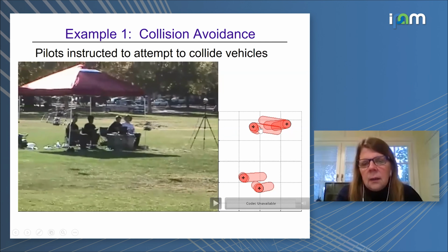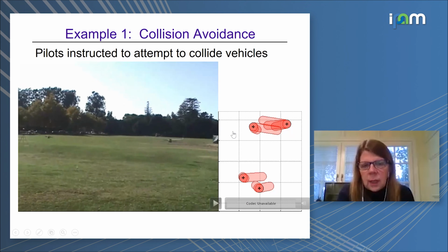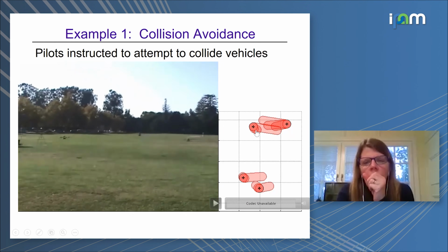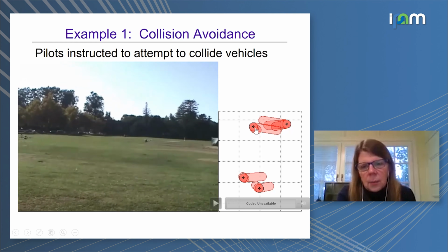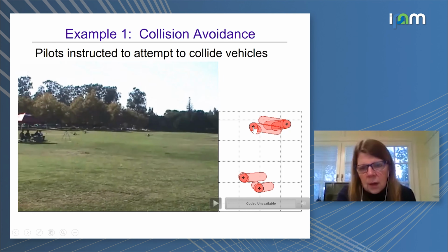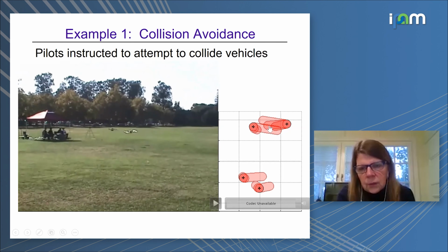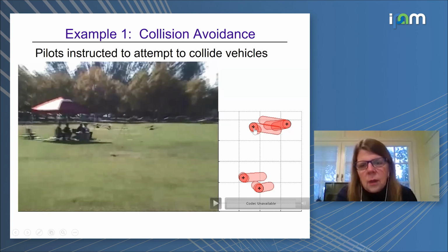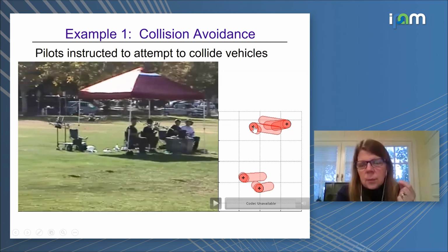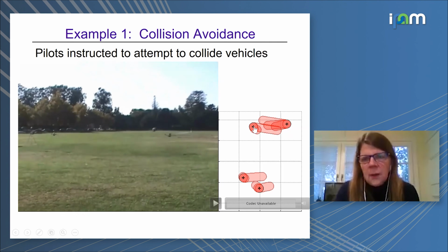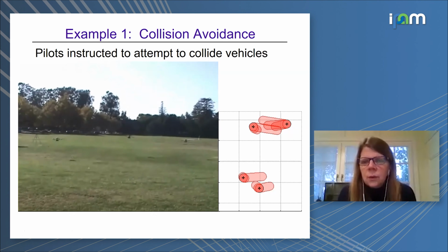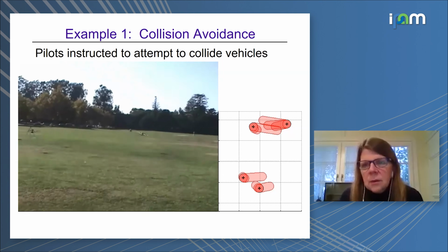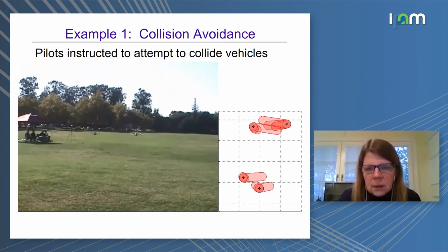What actually happens in this experiment is that the automation on board the aircraft, at the center that the other aircraft is on the boundary of, starts to execute the safe control law, the max over U control law, that also comes out of that Hamilton-Jacobi calculation.